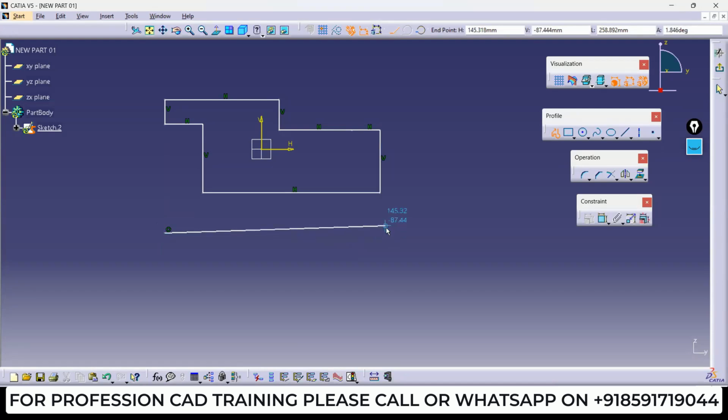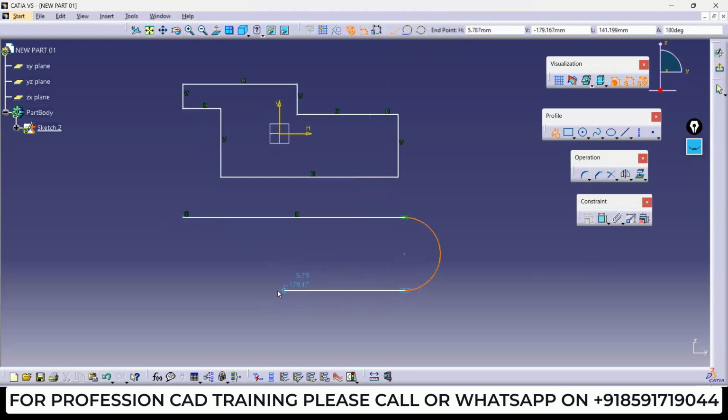But if I am deviating it, you can see the color change. It is turning white. White means it is not properly horizontal. It is turning blue means properly horizontal lines. If you click it, once you click here at the top, you can see in the sketch tools, you can get the arc options, tangent arc or 3-point arc. So if you go to the tangent arc, for example, second, this is turning into the tangent arc. And if I click here, again the line option will be invoked.